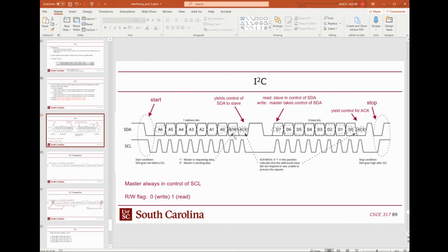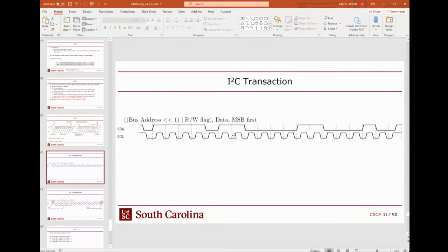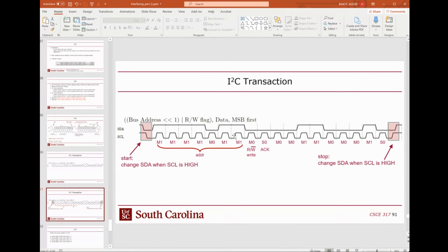And when I say control, I mean the entity that's actually sending bits on that wire is the one that's controlling it, right? So the idea is, you want to have one entity sending bits and the other one listening. Of course, that would require that these actual wires are both inputs and outputs on the chip. They're bidirectional inputs and outputs in order to implement the I squared C bus. Hopefully that answered your question. Okay.